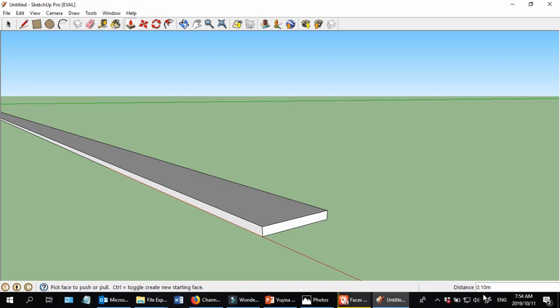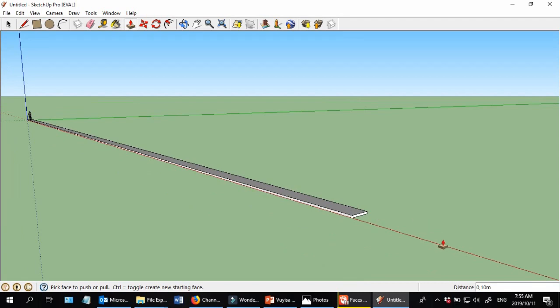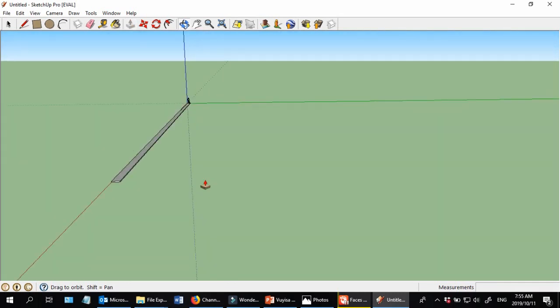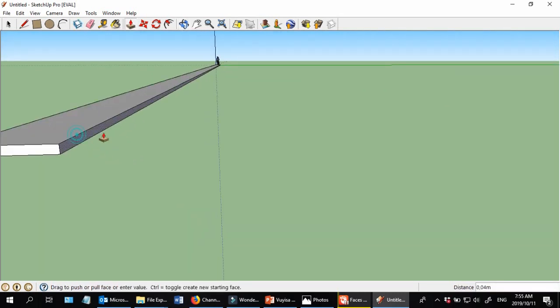All right. What you want to note about this number that you enter here is that this is not 0.1. This is 0, comma 1, and this is a distinction that you have to make on your keypad, because here you don't use the number pad. Okay, you don't use the point on the number pad. Instead, you use the comma on the keyboard. Okay, you use comma as if you were typing in a sentence. If you use the full stop, it will not be read. Okay, once we've done this, now we can extrude in this direction.